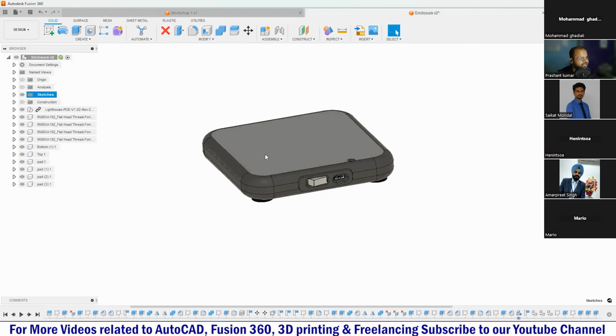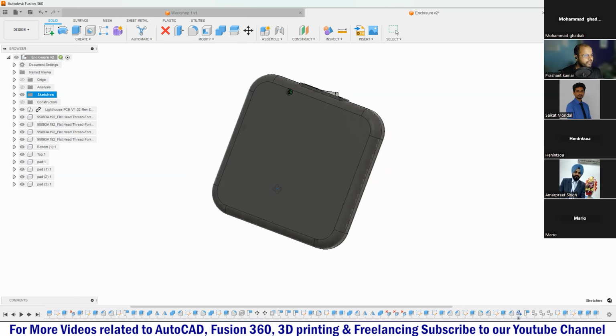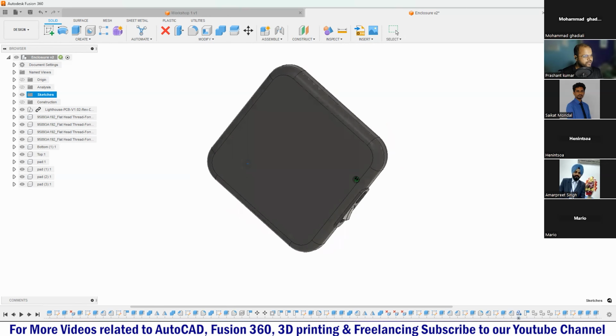If you want to do that, here you can see the moment I press my scroll wheel on my mouse, you will see this hand icon. This shows that you will be able to pan your model across your design space, right? And now if you want to orbit, like if you want to navigate across your 3D model without using the view cube, just press Shift on your keyboard, then press the middle mouse button like this, and here you can see you will be able to orbit across your 3D model.